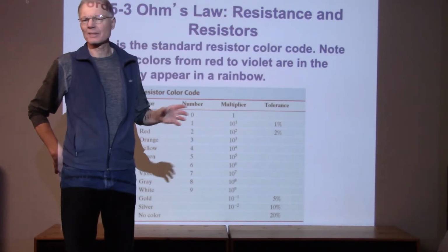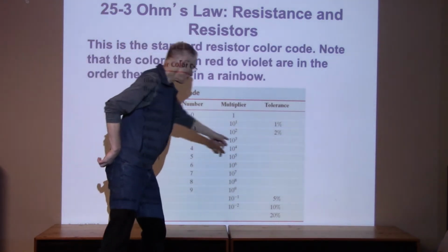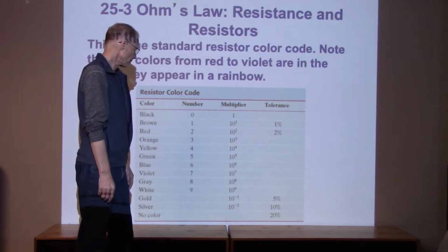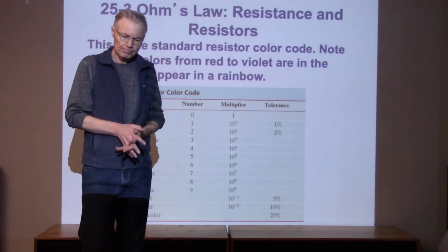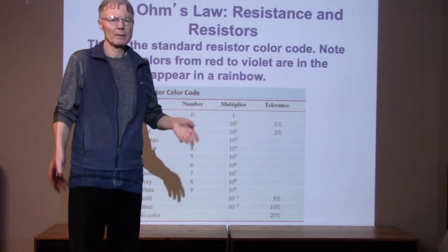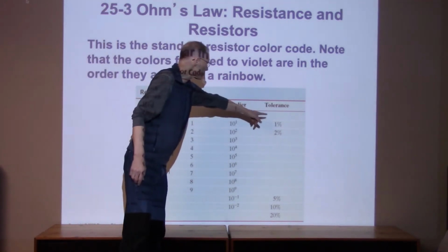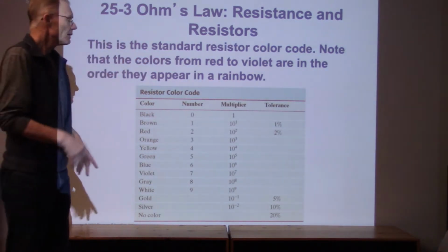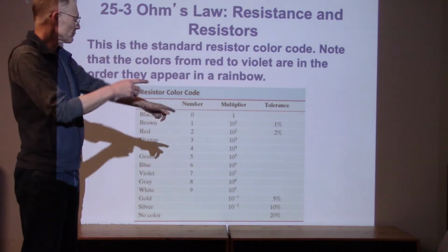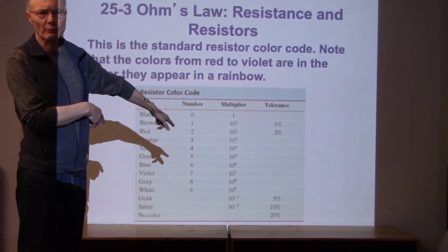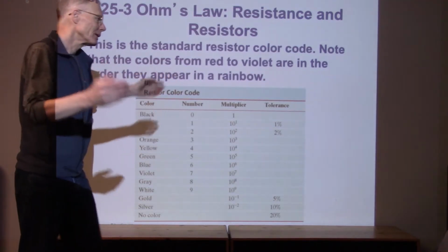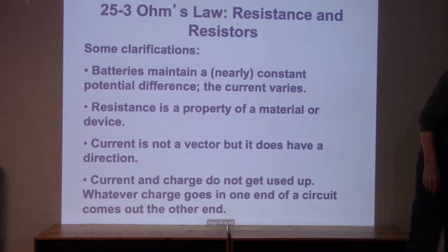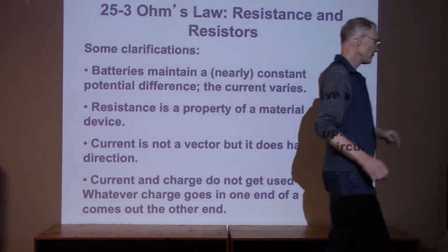If you've got a circuit and the resistance is not so important, then you can buy these variable 20-10% tolerance or uncertainty resistors. So the resistors are not being manufactured very carefully. And then for really high precision resistors, if it's got to be within 1% or something really tiny, they put a different color band on it. So it almost seems like you have to go out of your way to manufacture something that has 20% variability. But anyway, that's again for your information, definitely not something you need to memorize.